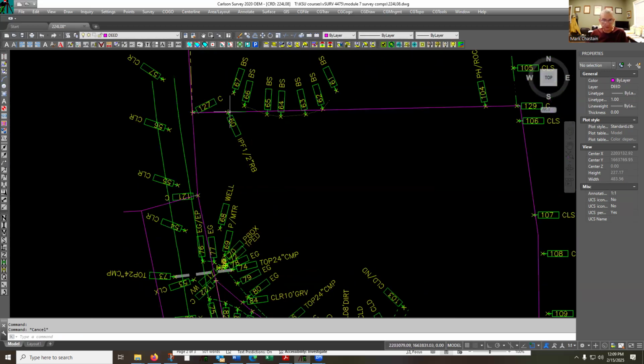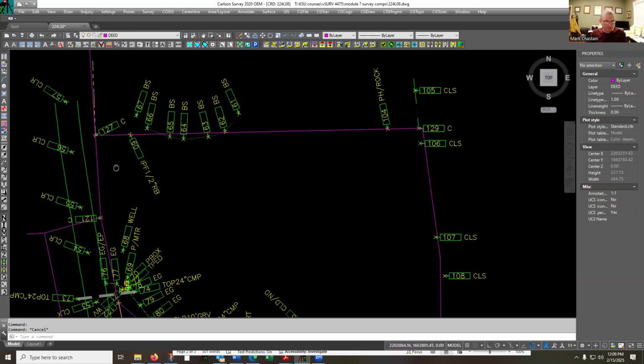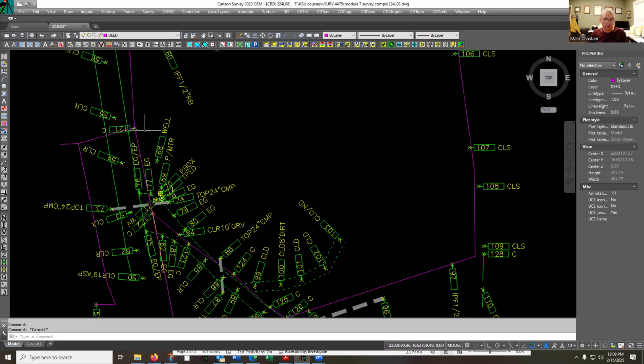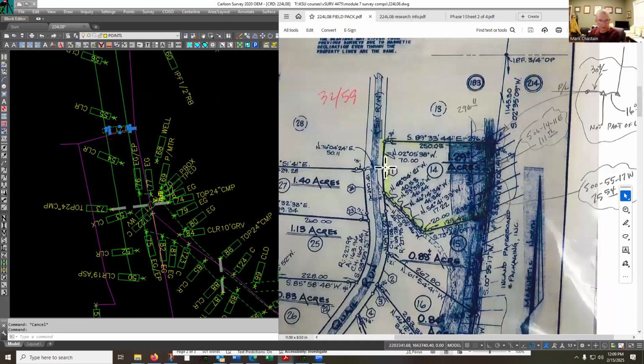So we've set on 60, we've got it rotated as best as we think we like it, and we would manually traverse from point 60 bearing 104 to 60, that 30 foot, that's 127, or we could have just picked that node off of it. That's how number 121 came to be down here, which is this point right here.